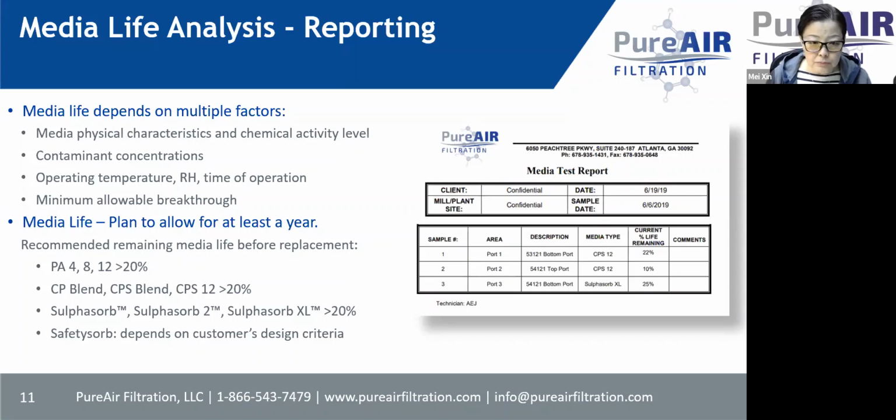And for Sulfur Sorb series products, 20% as well. That's a general guideline. If you have very strict odor control or emission control, you probably should increase the remaining media life, maybe 30%, 40%. So it's going to be case by case.